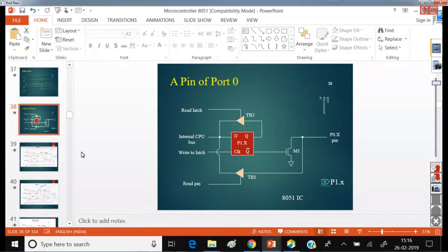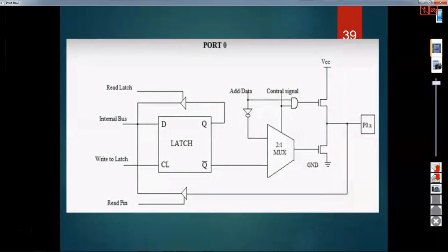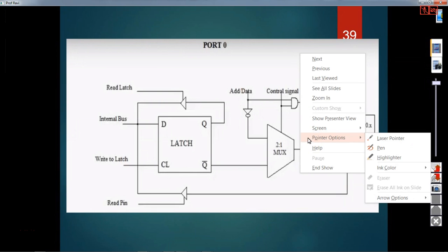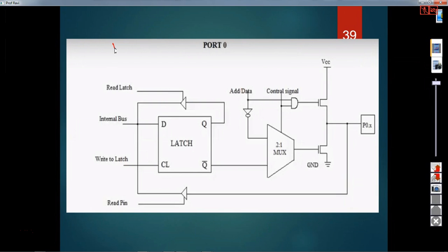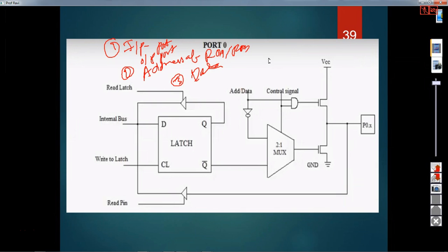Internally, as it performs 3 tasks: one, you can use port 0 as an input port or output port; two, you can use it to carry the lower address of ROM or RAM; and the third task is that it can carry 8-bit data. So port 0 does 3 tasks.